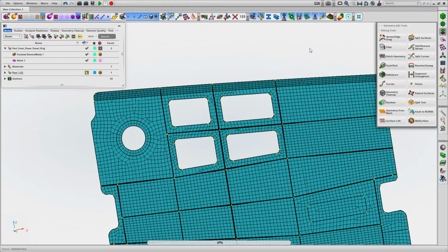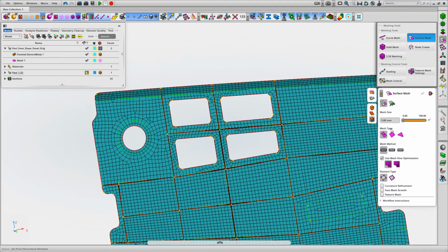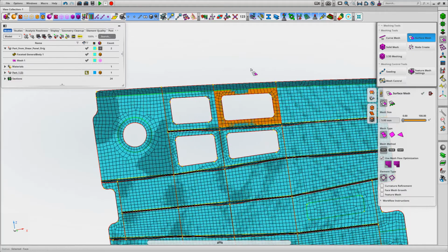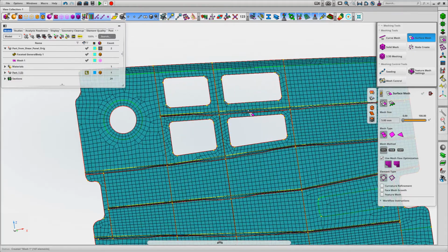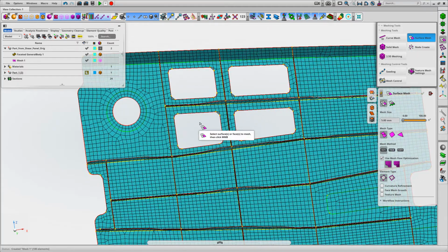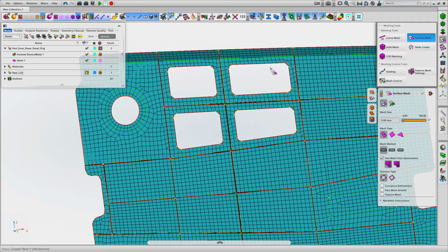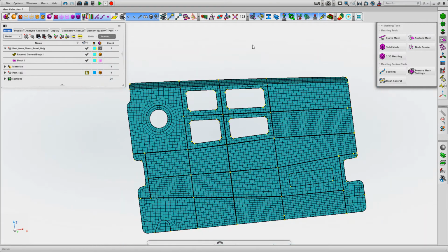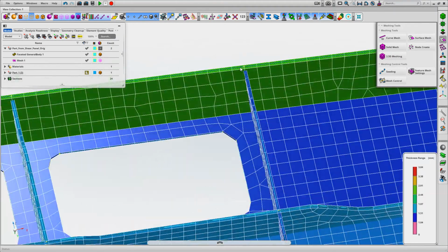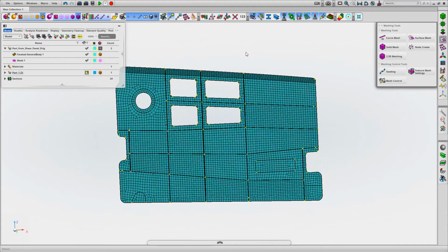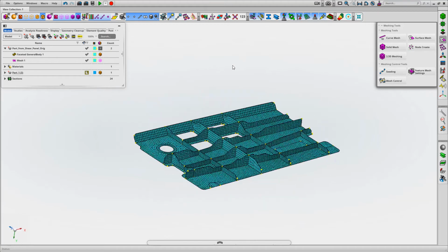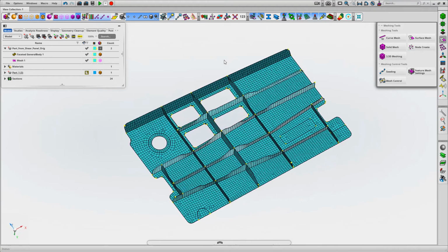Okay. We can look at tidying up the boundary mesh in those regions. Let's have a look, just see what this does. Yeah, much better definition. Clean things up nicely. There we go. So, tidied things up. And then we can look at the thickness again. So we've made the modification with minimal effort by using the underlying legacy mesh as the sort of surrogate geometry for the manipulation exercise.